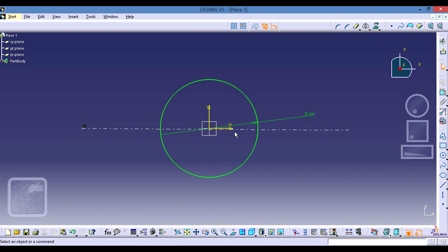If we go to our screen, we need this part of the line to be that size, 89 millimeters. We're gonna do the next thing. We're gonna click in this while keeping the control pressed. We're gonna click on this small point on the edge of this line.